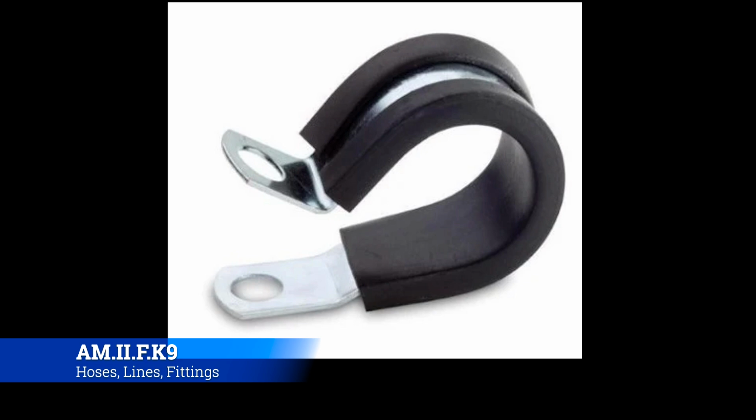Now these clamps are really good for a couple of different reasons. One, if you notice, there's a rubber grommet that basically cushions the hose and makes sure that it can't rub up against anything that's metal. It also is very proactive. Whenever you clamp down on this clamp and put it somewhere, it's not going anywhere. RTV could potentially fall off. Peanut butter tape could potentially degrade over time, and you're constantly having to make it move.